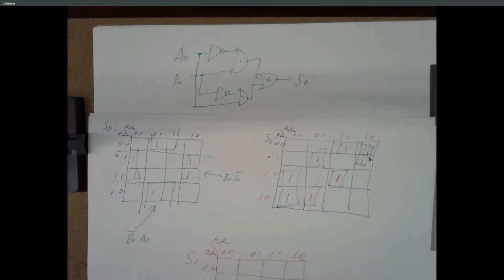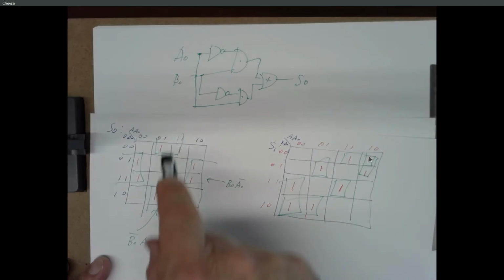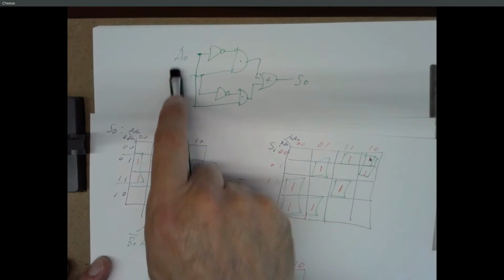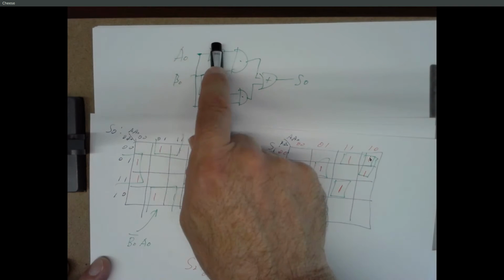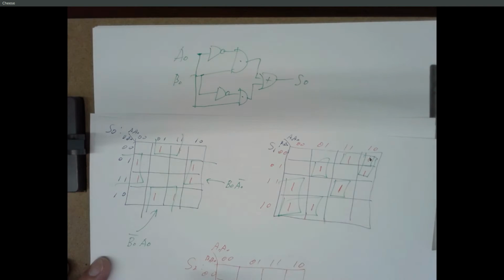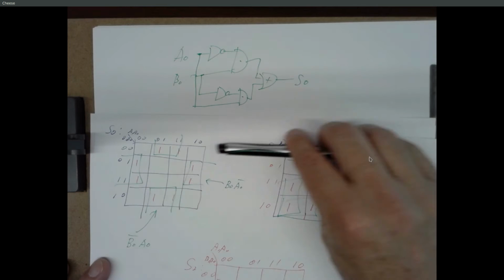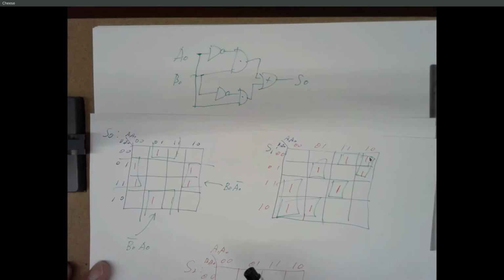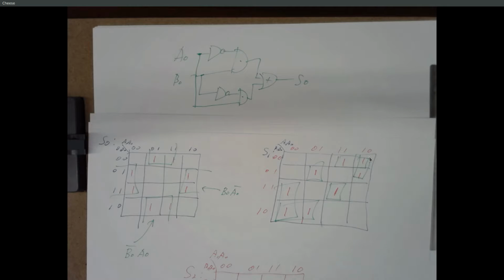And you would probably do this with your inputs going vertically. Put an inverter next to each one so you have A0, A0 bar, A1, A1 bar, and so on. And then bring your lines across the way we did week 1. And you'd get your 3 outputs, S0, S1, S2. We'll come back to that in a while. So that gives you a circuit.